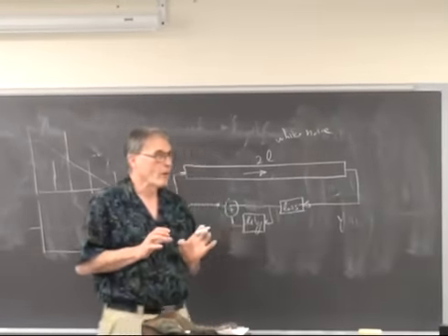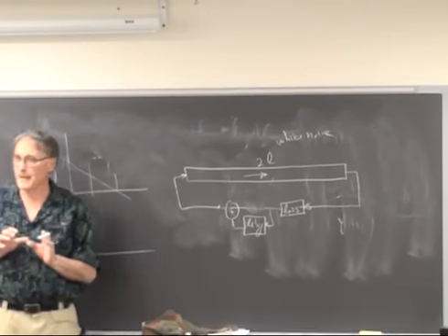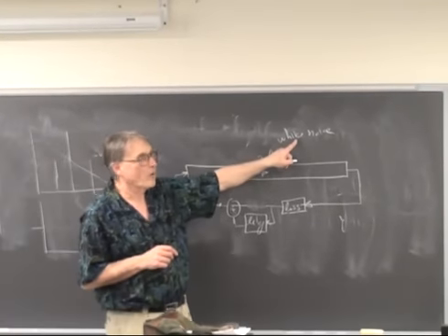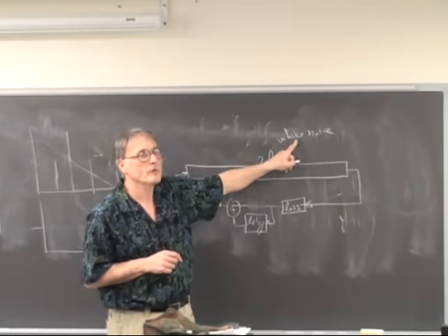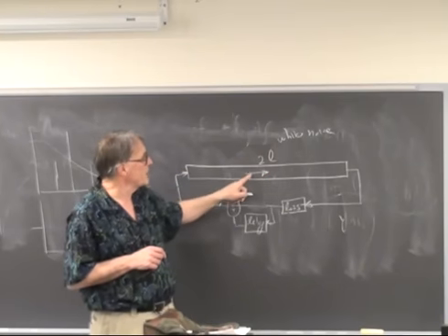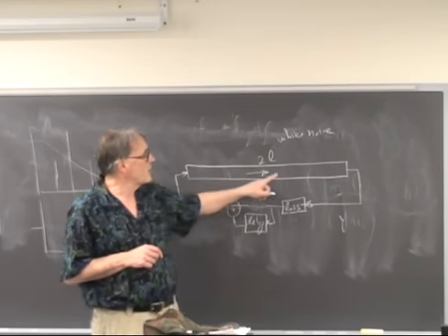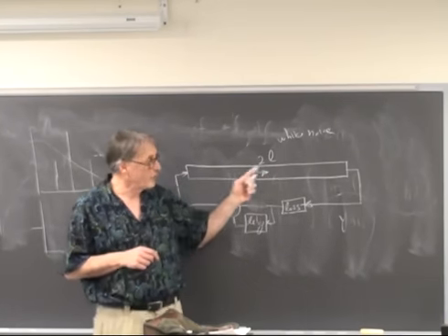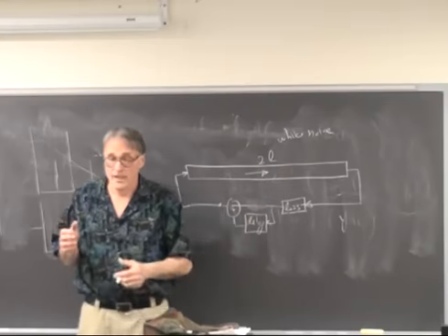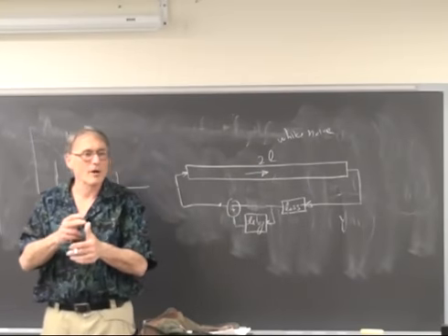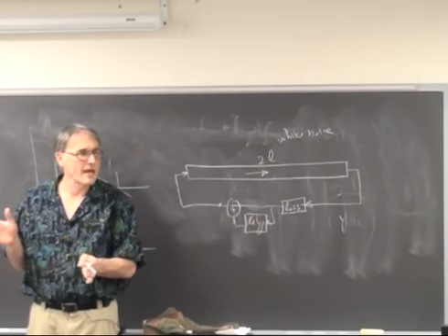Very broad bandwidth. If you filter the white noise before you load it into the shift register at time t equals 0, and then let it circulate, it sounds more like you hit it with the soft part of your thumb. You get a softer sound.